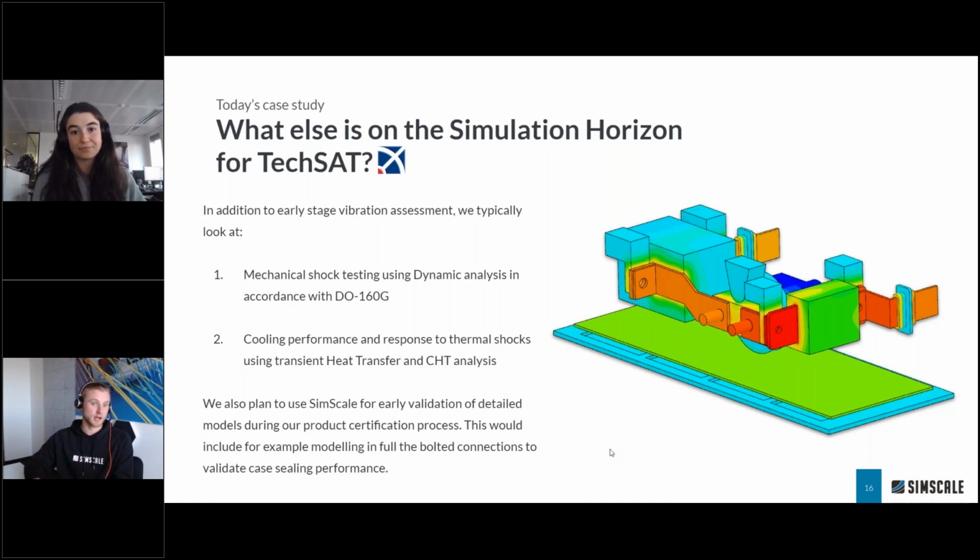So one with, for example, 1% critical damping, one with 2.5% critical damping, and one with 5% critical damping. And then you want to look at your worst case scenario. And when you're submitting a report, you can give a spread of what is worst case scenario, what is best case scenario, and your reality will be somewhere in the middle. But if you have material data available to you that contains the material damping coefficients, then you can directly apply them there. So I hope that helps.